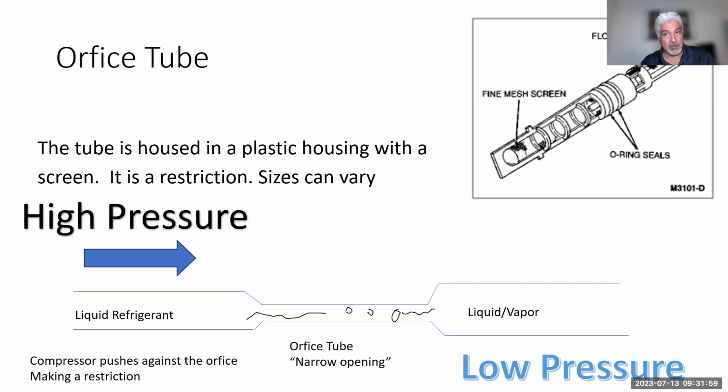That's why they're color coded. I haven't checked it lately, but it is available. So if I make the orifice smaller, you can actually raise the high side pressures. But since you created such a high side, that means that refrigerant will be able to actually run colder. A lot of guys cheat that way. So many people say, well, this is not the correct orifice tube that comes from the factory. You're right. But a lot of guys will cheat.